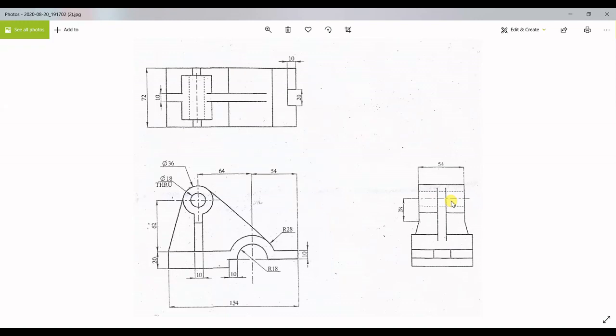Let us continue the discussion and practicing of a few sample exercises. I have a geometry of a 3D CAD model represented in the form of two-dimensional views. The motto of this particular exercise is to utilize the profile rib engineering feature in Creo Parametric and apply it to this particular model. On a closer observation of the geometrical views, we may notice that there is a presence of profile rib.